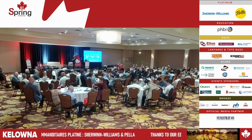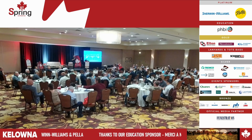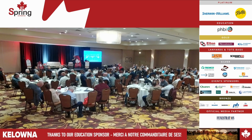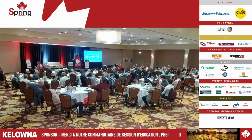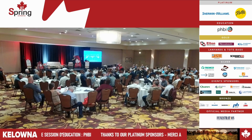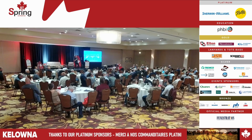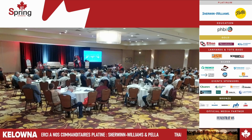Hi there. For projecting windows for Passive House Step 5, the path for most of us is going to be surface 6 low-E, which doesn't really come into play in Vancouver or the Okanagan, but if we get into northern BC or colder climates, what's the discussion around condensation? That's the problem, because I'm east of the Rockies, and surface 5 or surface 4 low-E is a real problem for condensation in certain areas. So I was wondering if that's on your radar at all or part of the conversation.